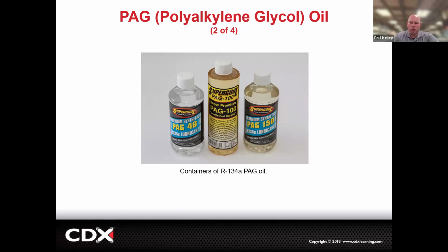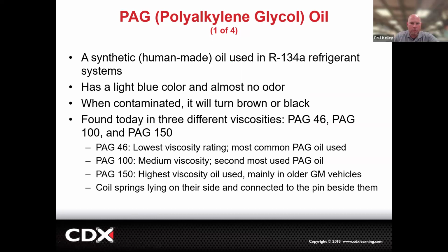Anyone ever seen these and they're green? That's what color you're going to see all of our oil. The reason why is because I personally add dye to all the oils. If we service a vehicle, I want dye in there. A lot of times we're servicing a vehicle because it has a leak. If you don't put the dye in there, you can't see the leak with a UV light, with a black light. You're relying on the sniffer and stuff like that. I personally just put the dye in the oil, and then every time I oil it, it gets dye. That's how I do it. You could do it how you want to do it.